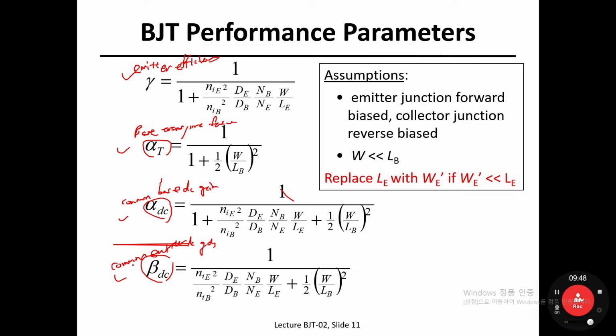Okay, so if you type HBT in a searching box, maybe the Google searching box or others, then you can see that heterogeneous BJT has been widely adopted in analog integrated circuitry. So N sub i, the intrinsic carrier concentration in base and the intrinsic concentration in emitter, would be different if we are using different materials. A silicon based PN junction is a homogeneous junction.